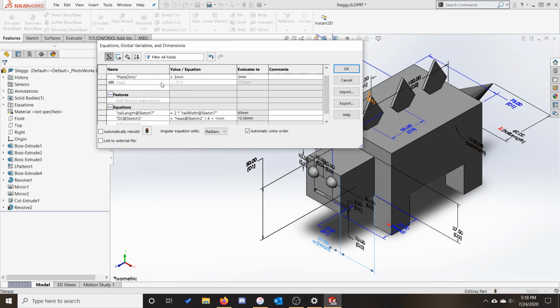Once again, if a value is going to be used directly, it's important that we specify units, in this case millimeters. If the value is going to be used as a ratio or as a multiplier for a value with units, we don't need to specify units. For example, if we want to use our global variable to specify how many times larger the height of the plate is than the width, then it's left unitless, as the value is multiplying a number that already has units. However, since we're going to say that the width is 4 times our global variable and the height is 10 times our global variable, neither of those values come with units, so the global variable is going to need its units specified. Now that we have our global variable, let's use it.